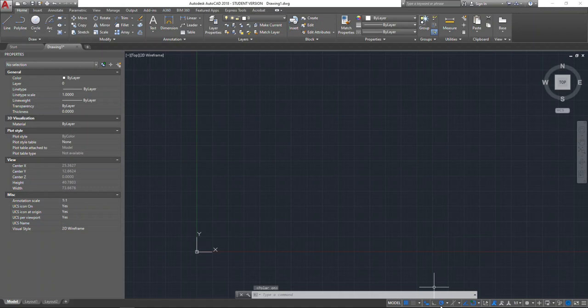If we click on this and use polar tracking, you can see it'll track, where it says polar 22.1538. It'll also track up in these directions, so it'll track basically in my 90-degree directions. If we turn polar tracking on to 45, 90, it's going to track out in my 0, then at 45 it'll snap, and then at 90 it'll snap, and so on.